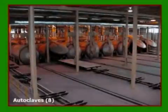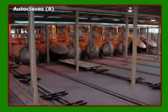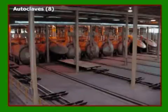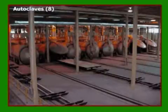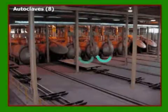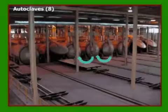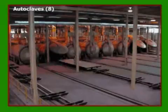Here is the most important part of the process, the autoclave. Also here we are very energy efficient. Before discharging an autoclave, which holds 12 bar of pressure and a temperature of 350 Fahrenheit for about 10 hours, we reuse the remaining steam by loading a new autoclave with the material, closing the autoclave, and then using the steam from an autoclave which is ready for discharging. So we push the remaining energy from autoclave to autoclave.